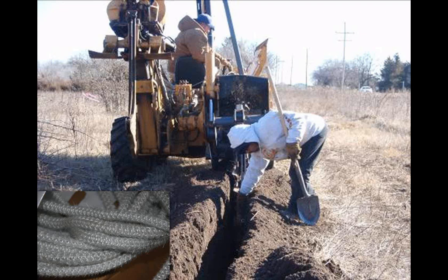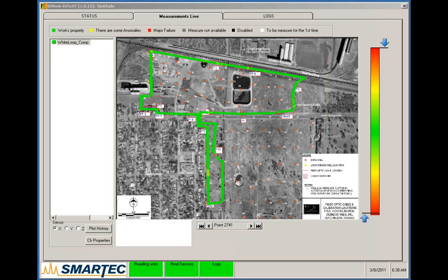The cable was installed by a trenching machine that cut a trench in the ground. The cable was then buried in the ground so that any early movement that could point to the formation of a sinkhole can be recorded and localized, so that again traffic can be stopped if it's close to a railway line, or other actions can be taken.